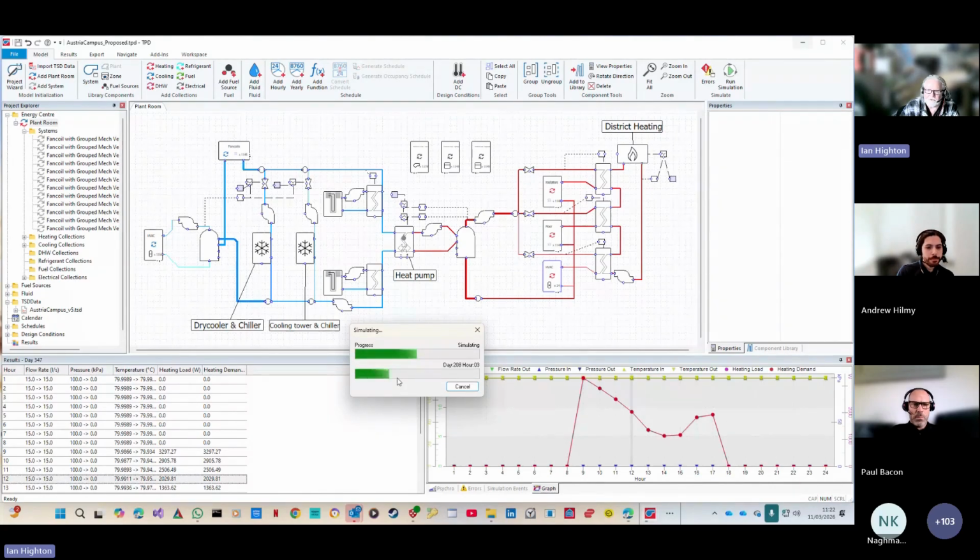So quite good. And you'll notice from this system, there's this heat pump sat right in the center. Sorry, can you see my cursor so you can see what I'm pointing at? Yeah, great. So this icon here represents ground loops, and in this particular model we've got 2 sets of ground loops, and then these funny S-shaped things are pumps, and these are heat exchangers, and you're clearly trying to use that ground heat source, heat rejection across this entire loop for the cooling circuit. And if the ground loops can't cope, then you've got a couple of chillers which will cut in and produce hopefully the set point that you're interested in.